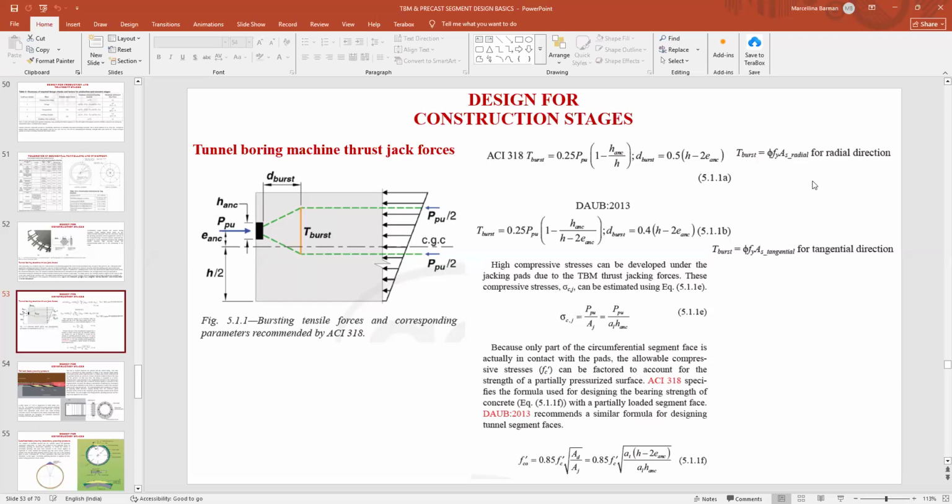This is not part of the permanent reinforcement. This takes into account the temporary loads. In the segment, if you consider only the main reinforcement, the quantity might be 85 kg per cubic meter. But finally, the quantity goes to 100, 115 kg per cubic meter because we are considering some additional bars to prevent cracking at the edge of the segment. Whenever the segment is being lifted, the additional moment is also taken into account by this additional reinforcement. So when the designer gives you the final quantity, 25% is automatically increased.